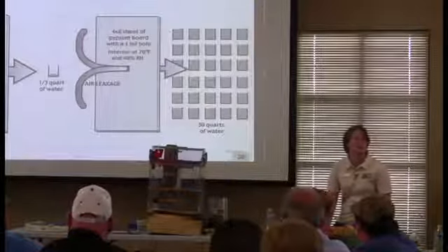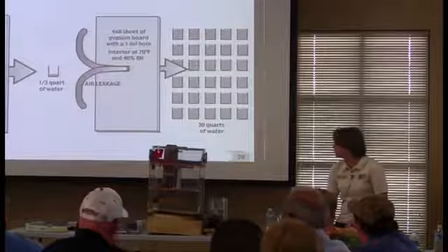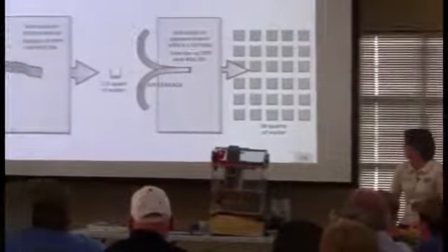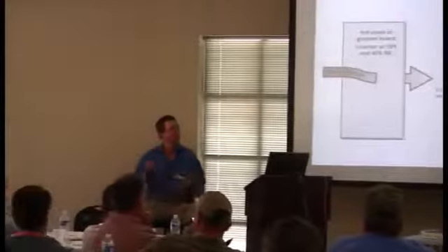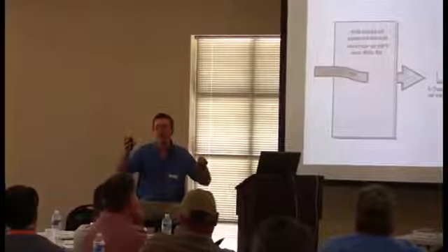That can cause a main problem. Air sealing is the big deal. The other thing, too, is that we don't live in a one-way climate, right? Water vapor diffuses from the side of the wall that has more to the side that has less.